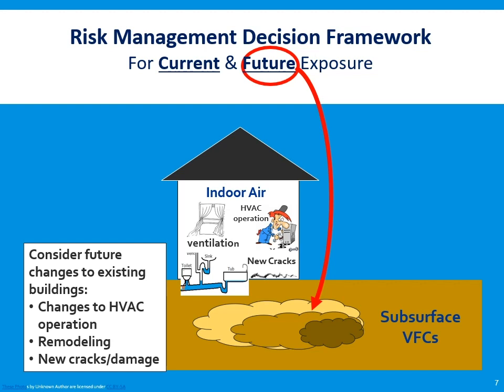For example, things to be considered are the size of the soil gas plume, how elevated the vapor concentrations are, and the lifespan of the soil gas plume itself. Hence, large soil gas plumes with high concentrations that last a long time could potentially pose a long-term risk to a building as the building changes in the future.